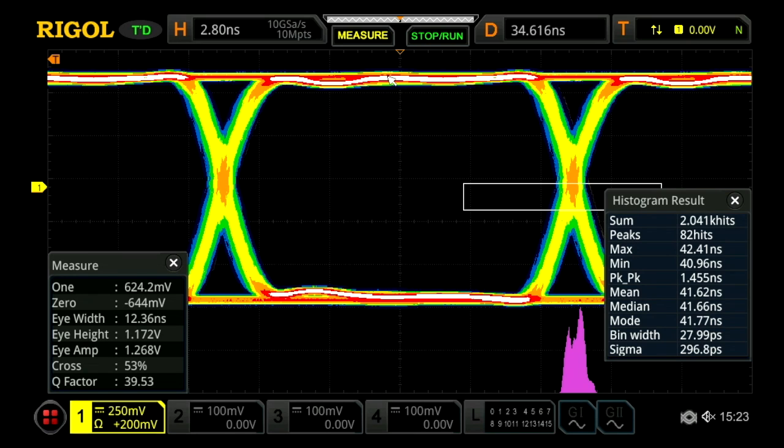The combination of removing the noise and improving the bandwidth has also really limited the total frequency and jitter noise as well. Now we have a nice open eye that allows us to go ahead and push our throughput by increasing our data rate if we need to really maximize the effectiveness of this serial data transmission.